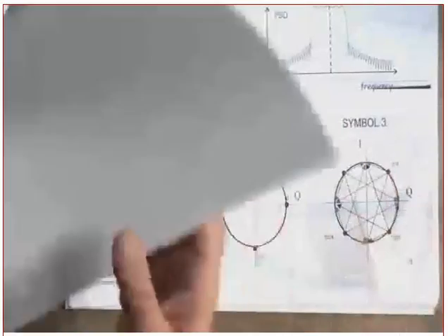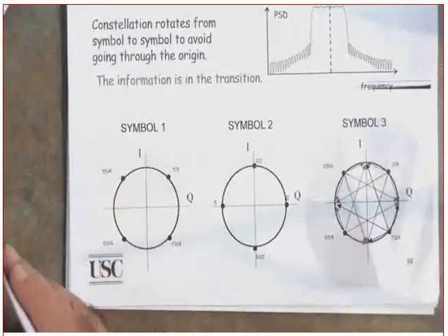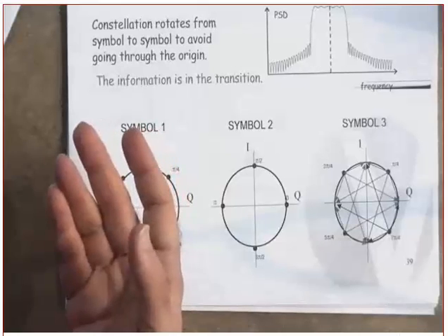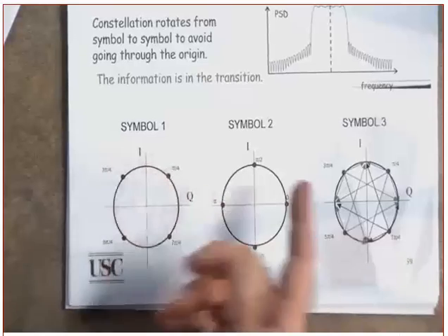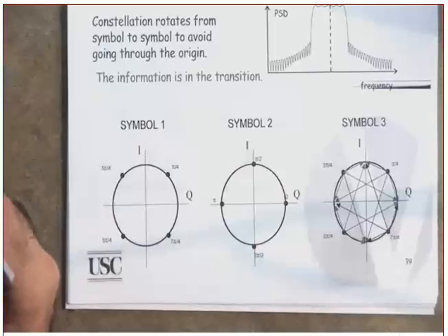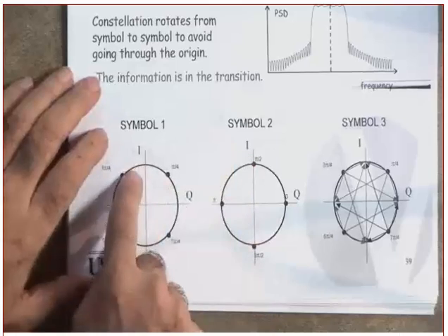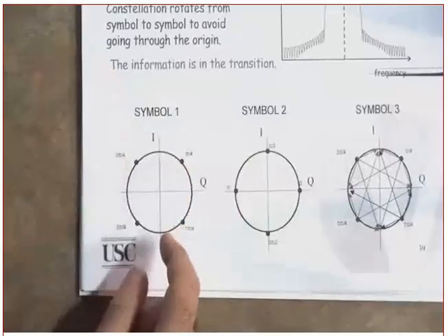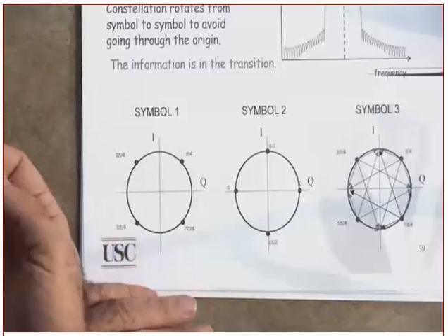Yes? What is the good thing about this? By the way, is it the same bandwidth? It's the same bandwidth. So you don't suffer from bandwidth. But what is it easier in? Cannot hear you. But you are the complexity, you are going to have two constellations. Clear? What do you mean no delay? You shifted this by pi over 4. Shifting is rotating, excuse me, rotating the constellation by 45 degrees.